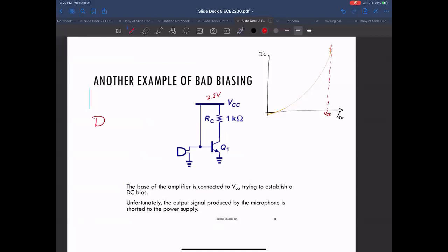So seeing that, the next step, you think, well, maybe what we want to do is, one, pull this up, but maybe not by 2.5 volts. Let's pull it up to some intermediate level, maybe someplace like 800 millivolts or something like that.